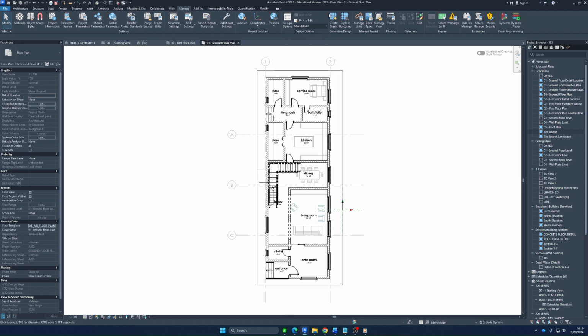Now, this tool can also be found at the bottom here, and if we look below here, we would see design options. This is also part of design options, to exclude options, but it's a temporary way of selecting things that are not in our main model.